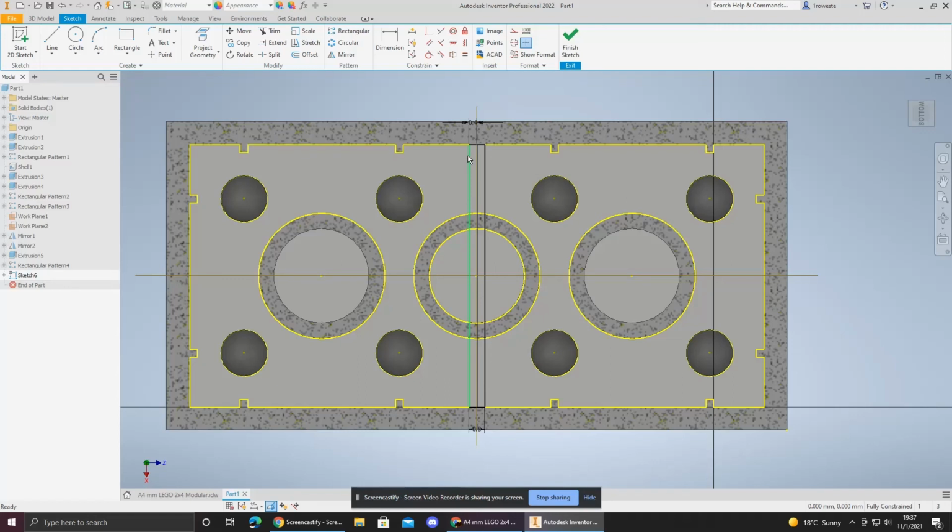Or using the following tactic may be a cleaner result. To demonstrate a slower, albeit more professional method, instead leave this line where it stands and utilize the offset tool. By pressing offset and then selecting a line, you can see that it creates a phantom version of it. We may now select a distance, in this case 0.4 millimeters, and in which direction we would like to set it. By pressing enter, we've created an offset at 0.4 millimeters, as you can see here.